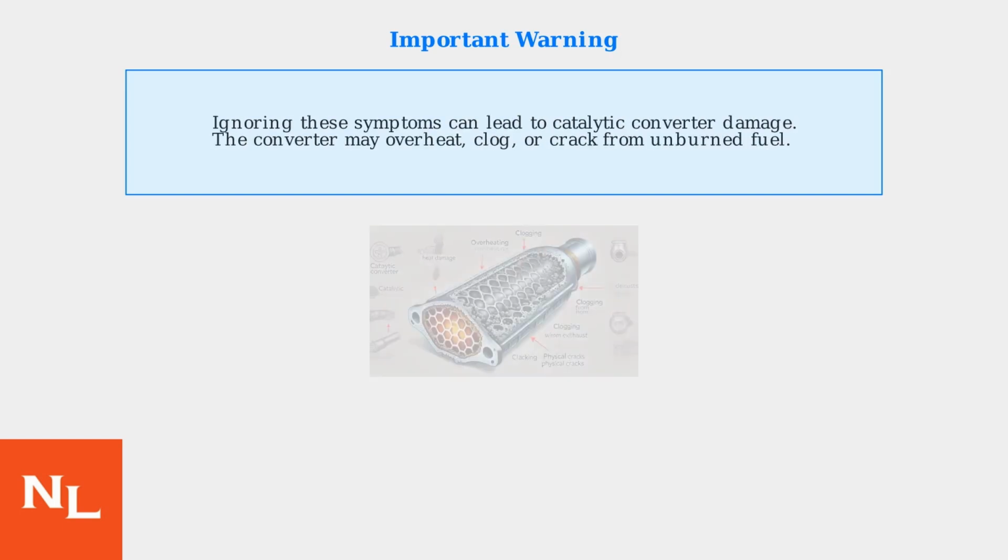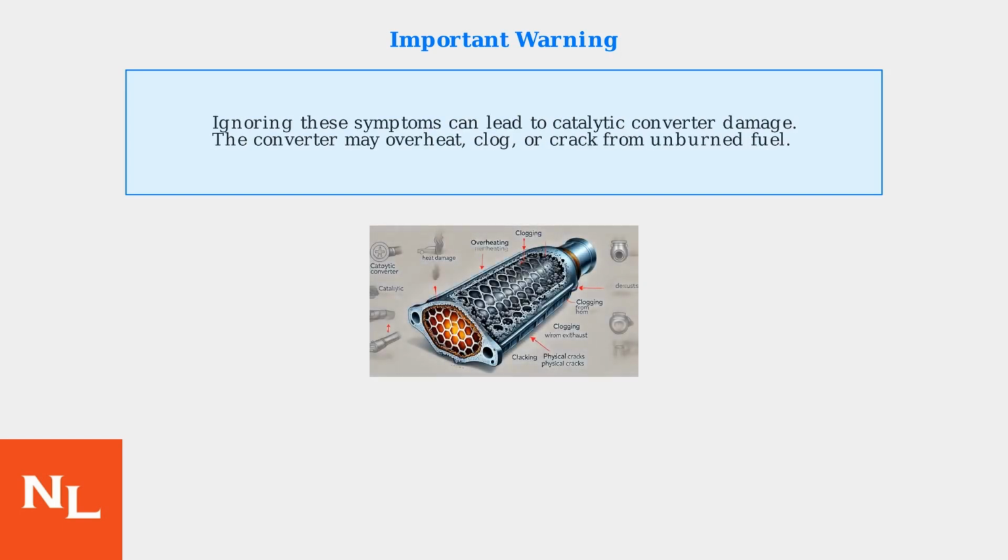In severe cases, the engine may stall or shut off unexpectedly. This can occur at idle or during low-speed driving when the timing issues disrupt normal engine operation. A critical warning: ignoring the P0024 code and its symptoms can cause serious damage to your catalytic converter. The converter may overheat, become clogged, or develop cracks due to excessive heat from unburned fuel reaching it.